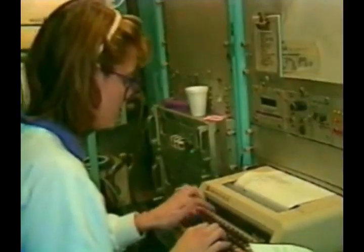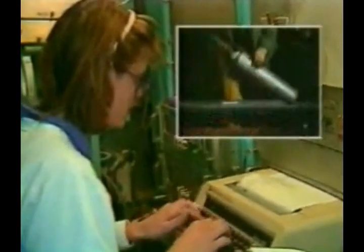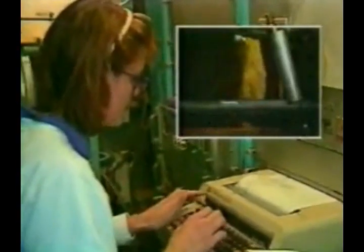Additionally, the logging crew must complete the after-survey calibration check. This involves repeating many of the same calibration checks that were carried out before the logging tools entered the hole, and entering these after-survey results in the tool check summary of the final printout of the logging survey. Such after-logging calibration checks are needed to confirm that tools responded consistently throughout the run.